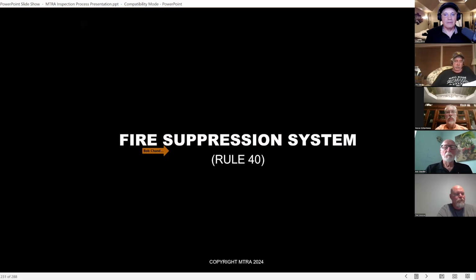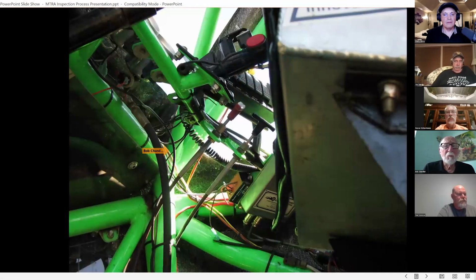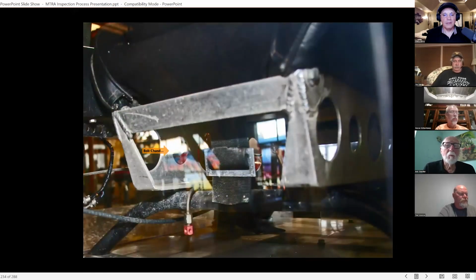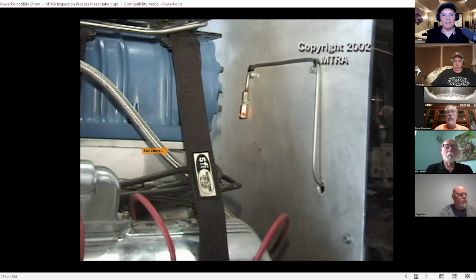The fire suppression system. Use the nozzles that come with it. With a small bottle, feeding too many nozzles doesn't work. The guy may have good intentions, saying I'll put some extra nozzles in this baby, put some out here, put some over here, well then the system doesn't work correctly. It's designed to work only with what comes with it in the box, which usually is 2 of those nozzles. That's a 3 nozzle head, but that counts as 1. And 2 of those is what the typical system will fire.